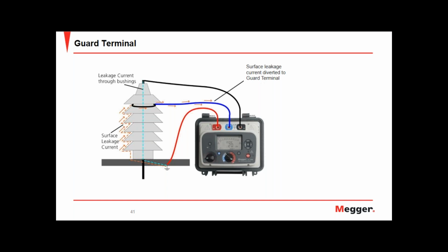So yeah, it doesn't have any negative effect on the insulation. By testing, it will uncover if there are weaknesses in the insulation. So if you've already got a weakness in the insulation, then the IR test is designed to see this. This is what we're looking for. It's not going to damage the cable. I'm saying cable as the example. The damage was already there.